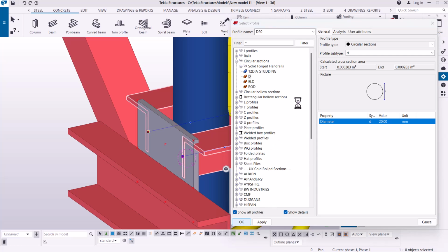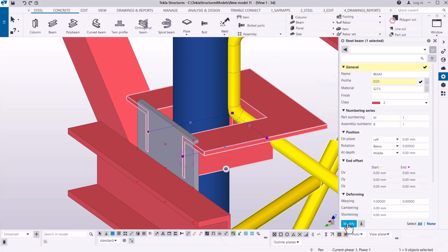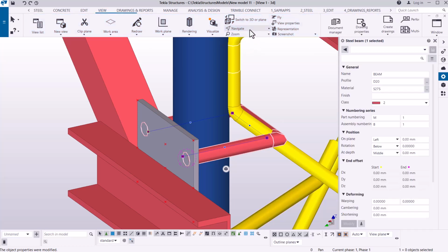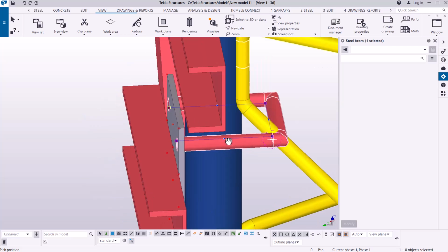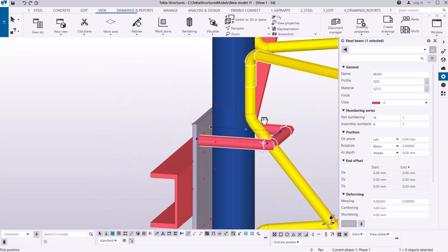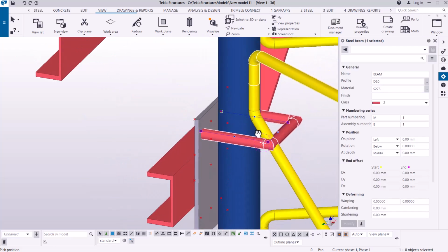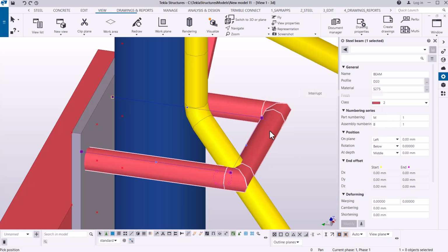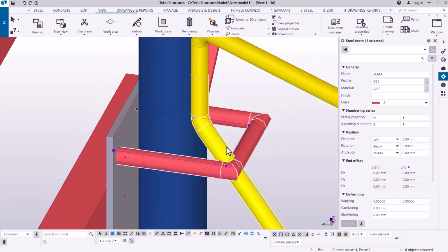Once I've given it an OK, I'm going to click apply. Once we are inside here, you can see it is taking a shape that, if you're not careful enough, you might start checking what this is, and we want to give it some chamfers here to make it a U profile. So you shouldn't worry why it's coming over beyond this brace.